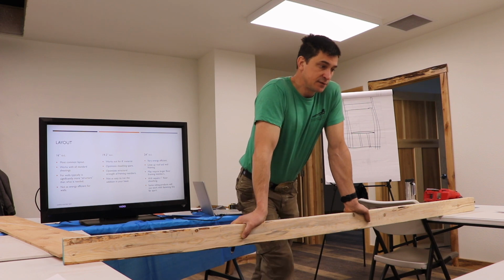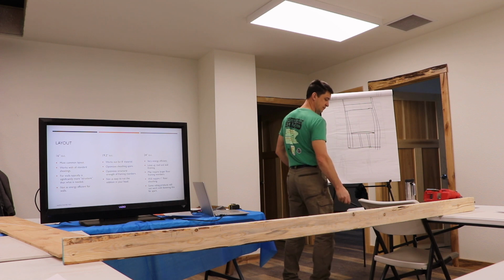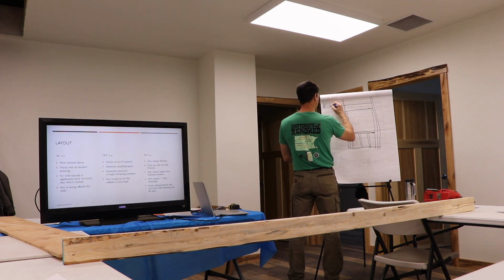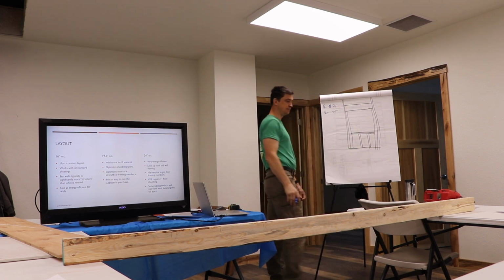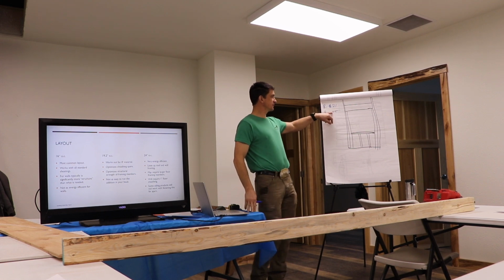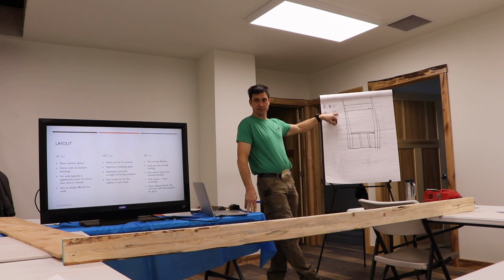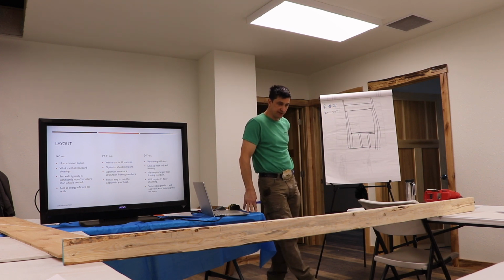And what that does, if my cavity is at, let's say, R21, and my stud is at R3.5, and I can reduce the surface area that's at R3.5 by 25%. We just made a substantially greater amount of our wall area at the higher R value.